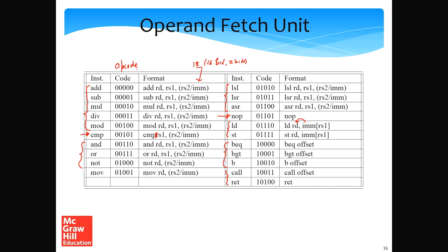So the question is, why have we given the opcodes to the instructions the way that we have? Let's take a look at the branch instructions first. Essentially, we need to look at decode complexity. If we take a look at the branch instructions, we'll see that all the branch instructions have been given an MSB of 1. So in that sense, it's very easy to find if an instruction is a branch or not. We just need to take a look at the most significant bit of the opcode and see if it's 0 or 1. So that's very easy.